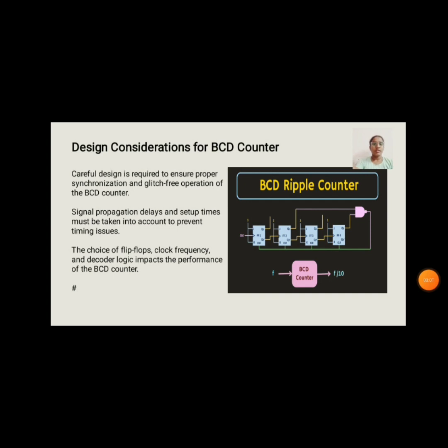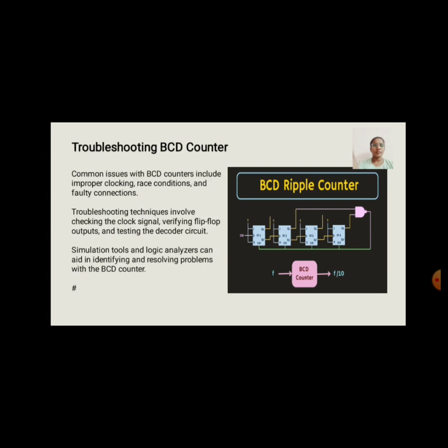Now I am going to discuss design consideration for BCD counter. Careful design is required to ensure proper synchronization and glitch-free operation of the BCD counter. Signal propagation delays and setup times must be taken into account to prevent timing issues. The choice of flip-flops, clock frequency, and decoder logic impacts the performance of the BCD counter.